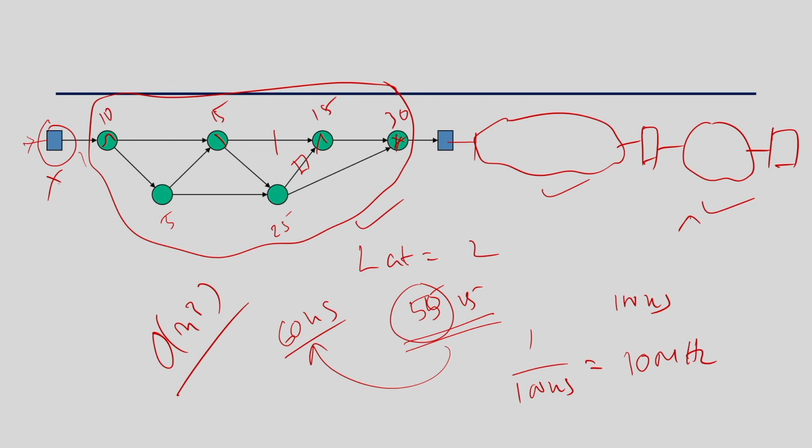Okay. So, what peripheral retiming does is basically move all the registers to the periphery, either to the input side or the output side, right. And then the whole combinational circuit can be considered together, and then I can apply more optimizations, and once it is optimized, I can retime the registers back to intermediate places, so that I can reach the target, right. So, peripheral retiming does two things. It first allows applying this combinational optimization to a larger circuit, because otherwise it has a boundary of registers, right.